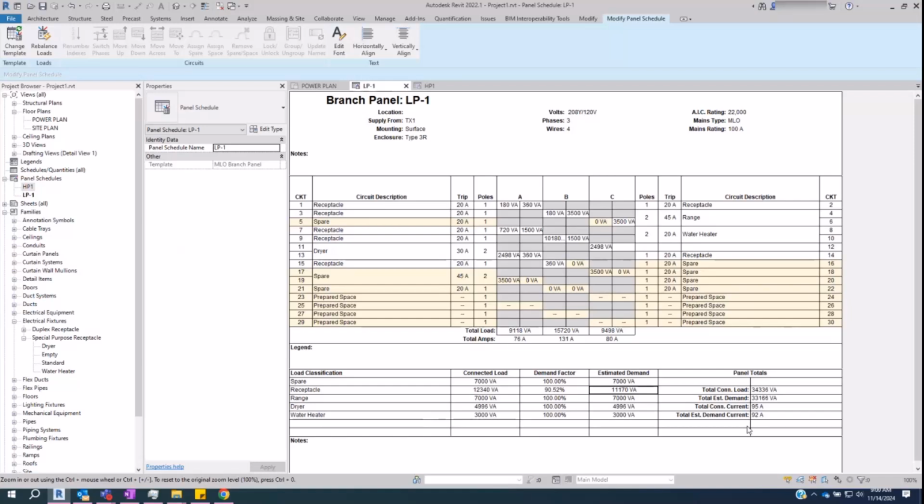No, yeah, it does. So either you're doing your panel schedules in Revit because the project's in Revit, and it does it for you. But like I said, you still double check to make sure it's populating right, because there are always glitches.